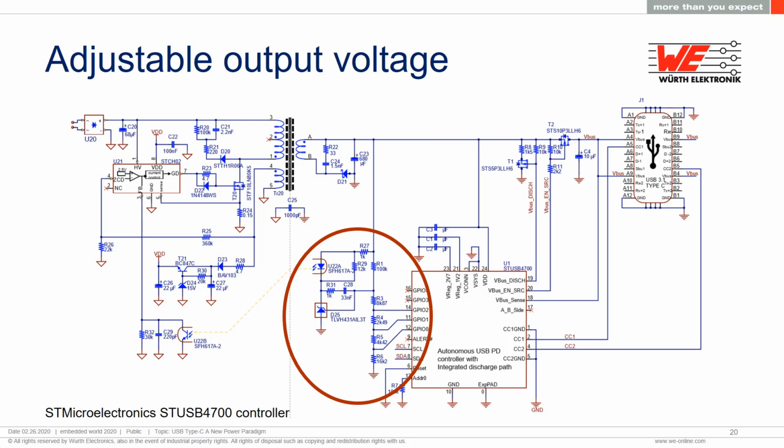The resistive voltage divider is set for each of the voltages, 5, 9, 15, and 20, and the GPIO pin shorts a tap to ground to give the right feedback voltage. This works because in a flyback transformer, the output voltage is not tightly coupled with respect to the turns ratio.